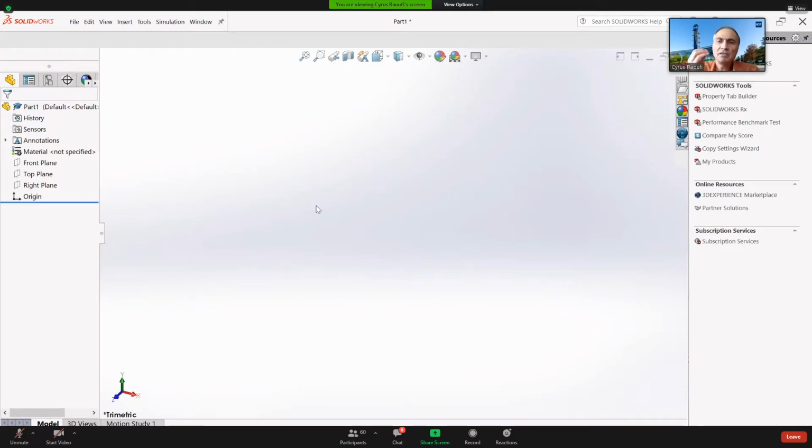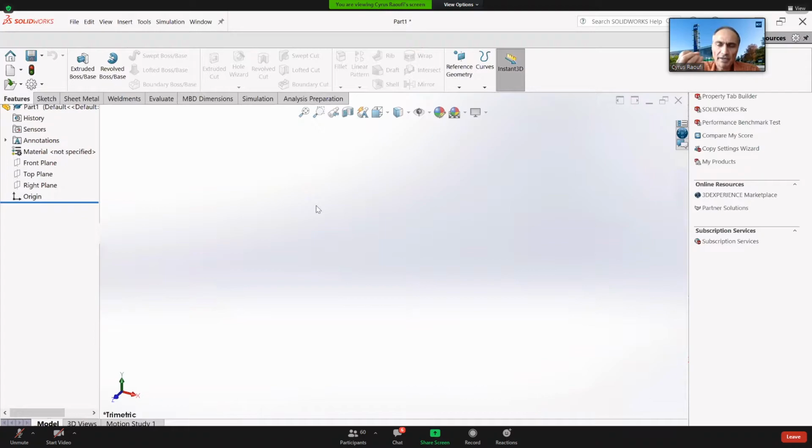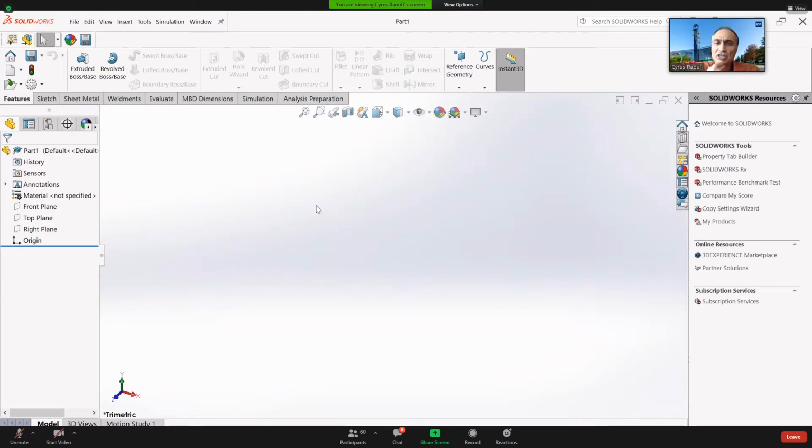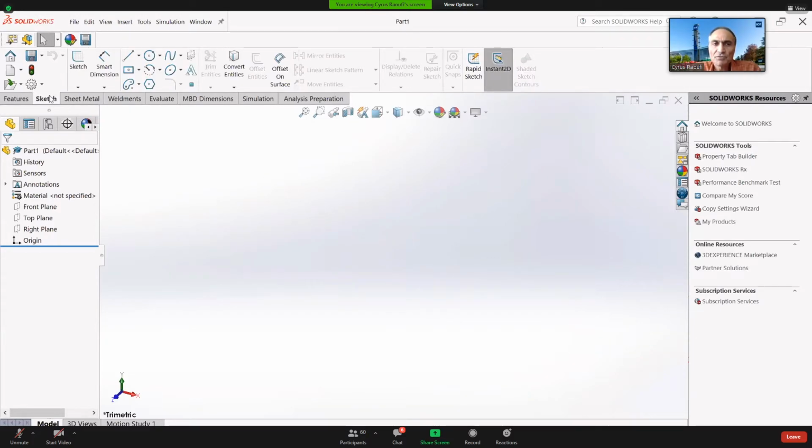As I said, for 3D, when you want to create the 3D truss, or later on in chapter 5, we have 3D frame, you need to create a 3D sketch first. Otherwise, you cannot create a 3D truss. In SolidWorks, if you go to Sketch, here we have 3D Sketch. Make sure you select 3D Sketch, not Sketch. If you select that one, it says 3D. And you are in the graphics area, in the isometric view, which wasn't the case for 2D sketch.